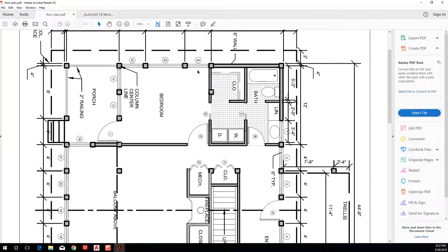And the things below that are going to have lesser pen weights, lighter pen weights, and show lesser importance, right? So in this room, the doors, the walls, the windows, all very important architectural elements, okay? When I look down below the 3 foot cut line, I'm going to see furniture next, right? So that might have a medium, lightish pen weight in this case. And then I look down to the floor and I see carpet tile, right? So we'd have a carpet tile pattern on the floor, and that would have the lightest pen weight of all of ours, okay? So when we're looking at a set of drawings, that's how we read them.